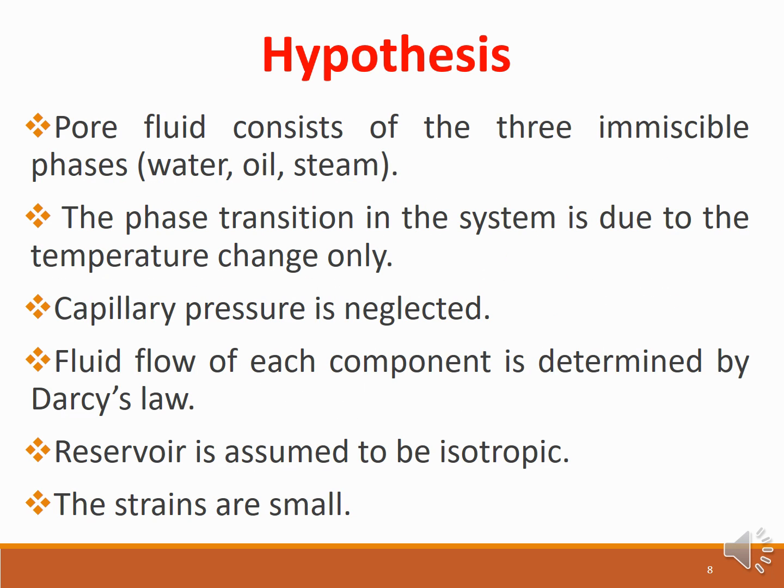Therefore, the mathematical model of oil filtration is based on the following hypothesis. Pore fluid consists of three immiscible phases: water, oil, and steam. The phase transition in the system is due to the temperature change, and capillary pressure is neglected. Fluid flow is determined by Darcy's law, the reservoir is assumed to be isotropic, and the strains are assumed to be